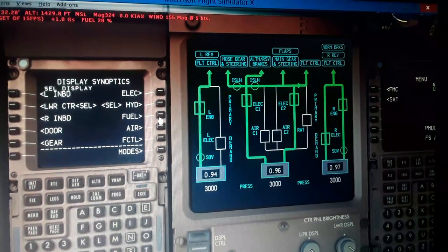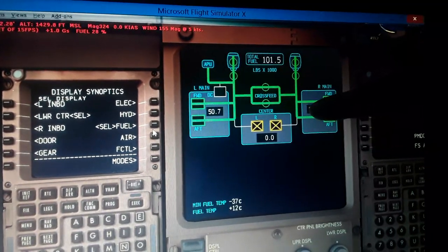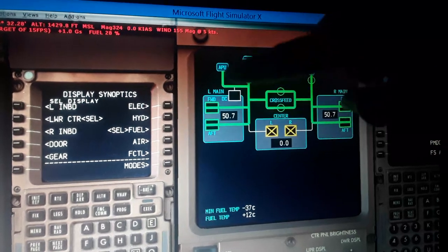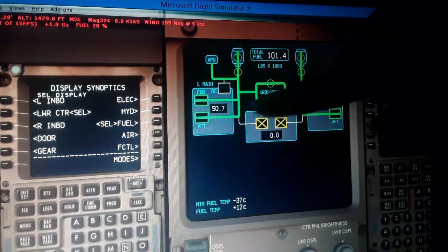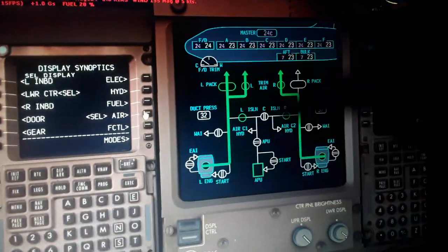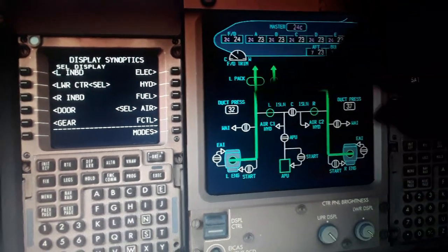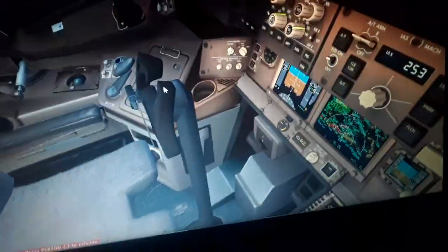We have also the fuel, left and right engine, the left and right wing fuel tanks, forward and aft pumps, the crossfeed valves, low and high pressure fuel valves, and the APU is taken from the direct current motor, and also the center tank is empty with yellow crosses. The air bleeder from the left and right engine, cabin pressurization, wing and engine, also the APU unit for starting the engine. Flight control system, you can see we can move around flight controls like this.